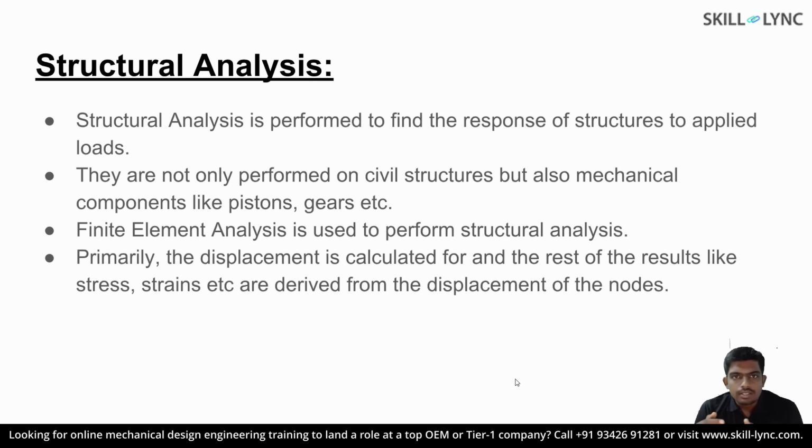So structural analysis. The term structure not only refers to civil structures like bridges and buildings, but it can also be used to refer to the mechanical parts that we often use in an industry. To understand the stress and strain produced by the loading on these mechanical structures, we perform finite element analysis to understand the behavior. Here in a finite element analysis, the unknown displacements are initially found out and then they are resubstituted back to get the reaction force and other derived quantities like stress and strain.